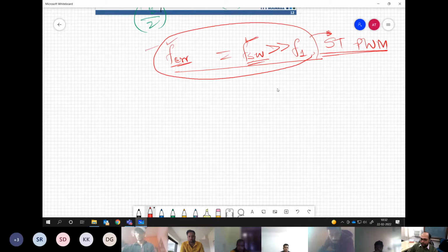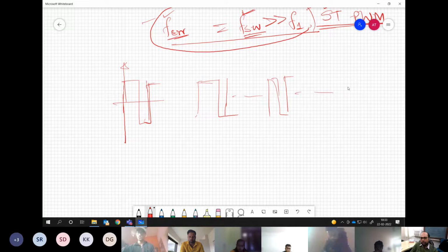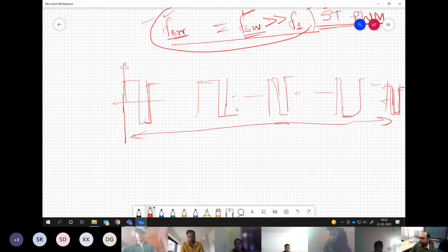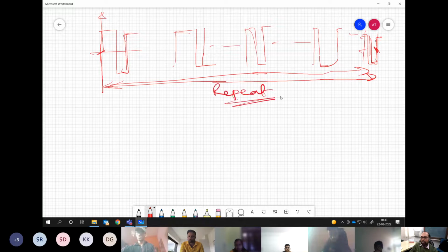Now, we understand that we have a pole voltage with, let's say, 50% duty ratio, which slowly goes to a higher positive width, gradually comes back to 50% again, then goes to only, let's say, 10% width, and then comes back to 50%. One thing that must hold in this whole PWM waveform is that, to have a fixed fundamental frequency, it should repeat itself after every fundamental cycle, which is what we have seen in the case of low switching frequency also.